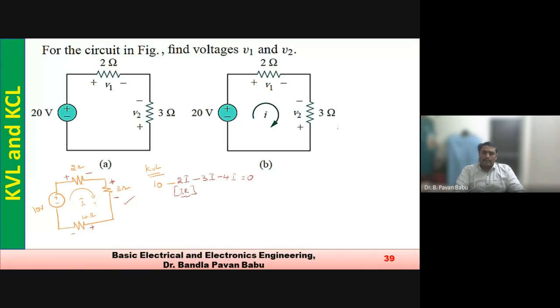In case of parallel, the voltage will be same. So that is the reason all of your appliances, when connected to a voltage, the voltage remains same. For example, an AC is connected at 240 volts, even an LED lamp is connected with 240 volts. So the voltage remains same, but the individual current drawn by that particular appliance is different, since it is a parallel circuit.